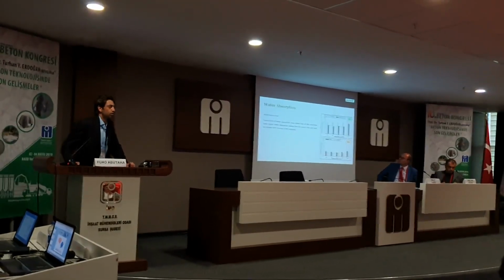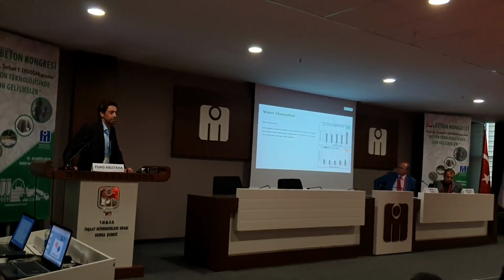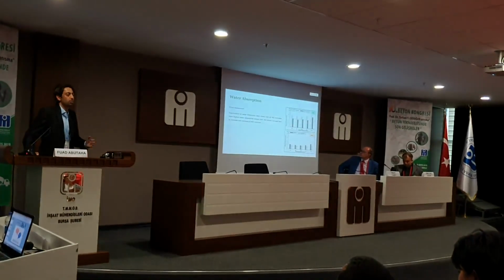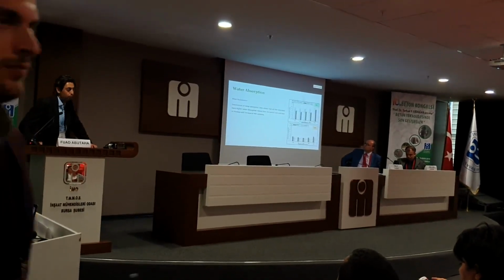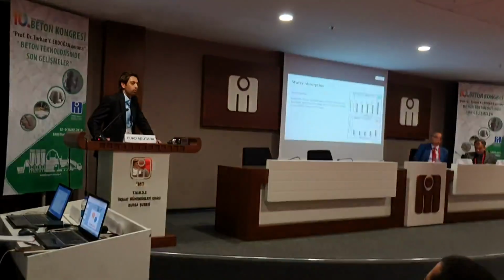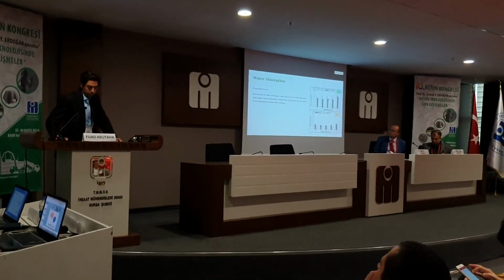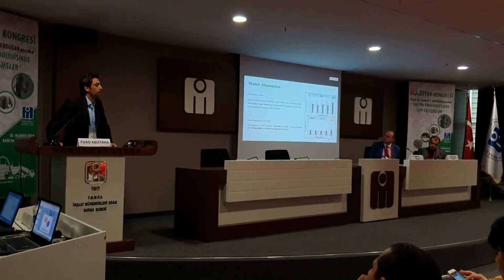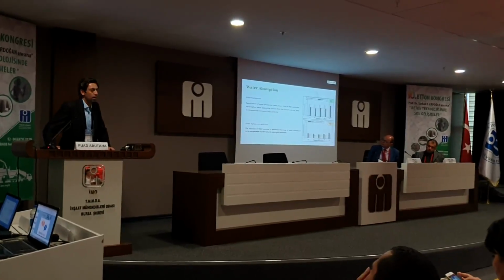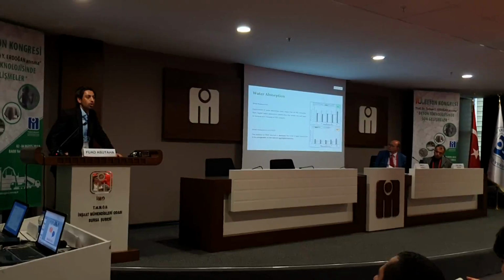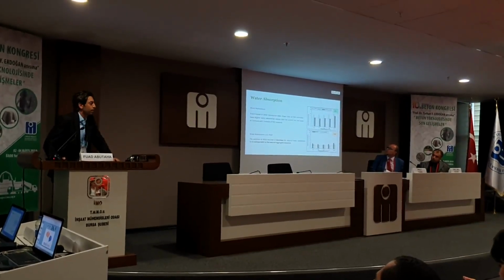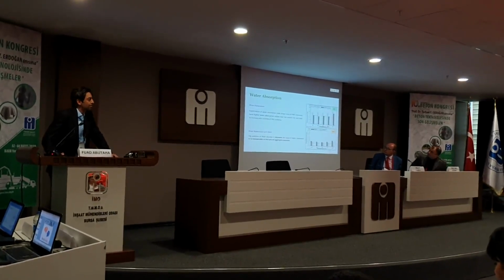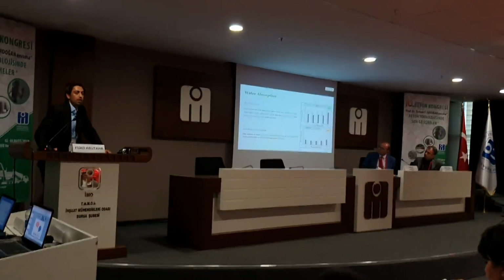The water absorption: as I have just mentioned, this material is porous with a lot of voids, so it tends to absorb more water. So with the increase of the POC contents, the water absorption increased. But after incorporating the POC powder, there is a significant reduction in the water absorption, and this is attributed to the reduction of the water to binder ratio, because the POC powder, the filler, was additional, not a replacement of any material.